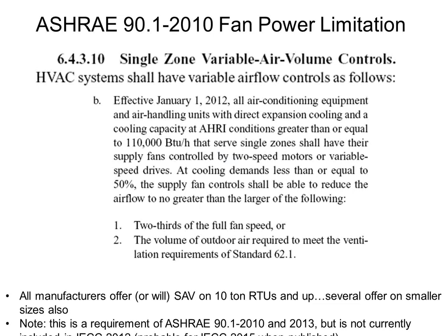Now, a lot of areas don't follow 90.1 as their code. They follow IECC. IECC did not put this into their code, so you don't have to do it in a lot of spaces, right? But if you are on 90.1, you have to do it. Some cities have adopted 90.1 in some states, and more interestingly, if you're doing a LEED project, 90.1 is a prerequisite for compliance with LEED. So if you want to even have a chance at getting LEED status, you have to do everything in 90.1, which means you definitely have to do staged air volume on any units, and this is rooftops or air handlers, any units that are larger than 9 tons. You've got to have the ability to step down the airflow when only one stage of cooling is running. So it's required.